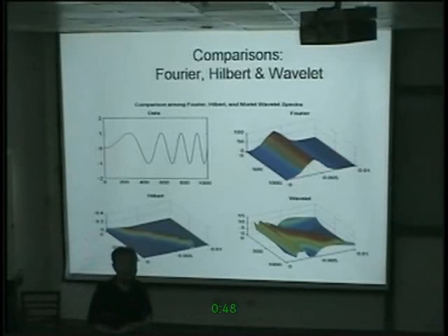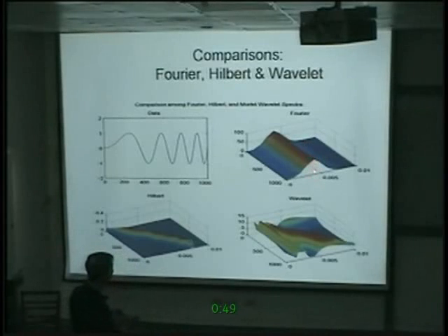I have 1024 data points. You have 512 sine functions. You ask them, so which one is this particular frequency? This particular frequency turns out to be the mean frequency somewhere here. And then all the others are sine waves from beginning to end. I don't see that frequency at all. But miraculously, if you add these 512 sine waves, you will recover this function perfectly, because Fourier is complete.